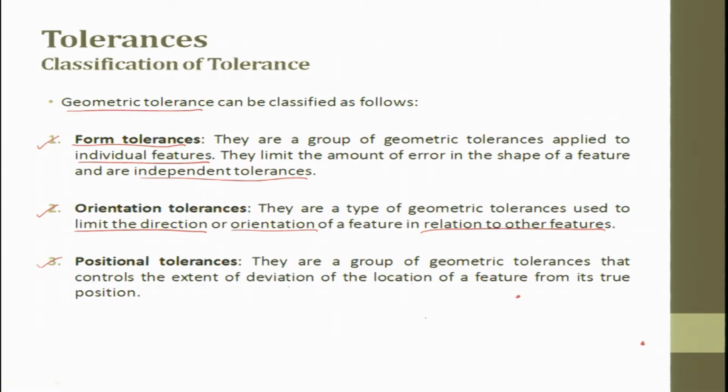So, orientation tolerance and position tolerance, these two along with form, these three play a very important role when you do assembly. When you produce a part from an interchangeability point of view, we talk about unilateral, bilateral, compound. But the moment geometry comes into existence, it is more focused towards assembly.